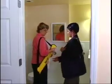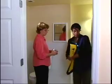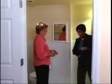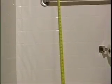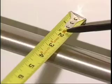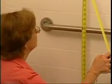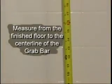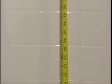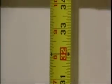In surveying this unit, we will proceed from the front door, moving always in one direction. In this case, we move to the right. The first room that we will survey is the bathroom, starting with measuring the height of the side grab bar at the water closet, and then we will measure the space between the wall and the side grab bar. When measuring the height of the grab bar, measure from the finished floor to the center line of the grab bar. The center line of the grab bar should be mounted between 33 and 36 inches above the floor.